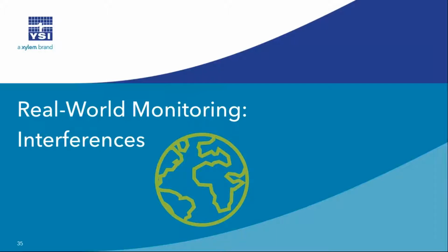That's a sound practice. The real challenge is if and when you encounter a situation where that slope deviates from what you're used to seeing, you're not going to know why. You're not going to know if it's because the sensor was drifting. You're not going to know if it's because maybe you messed up an extraction or if something else is going on in the environment. Now, the clue to help you figure out why would be to check the 0 point